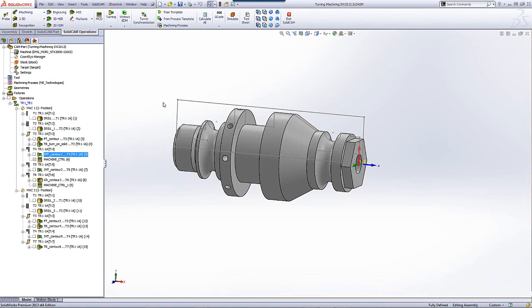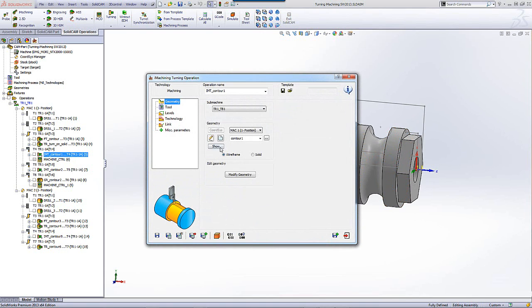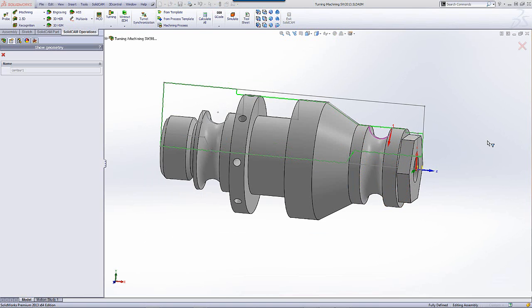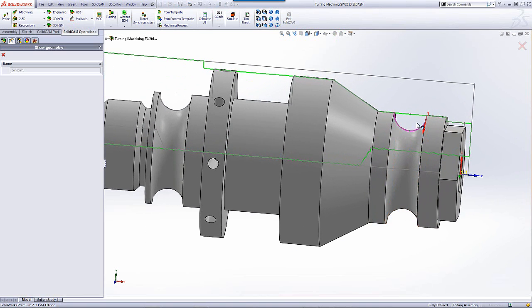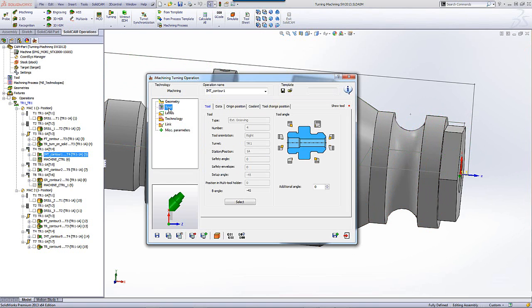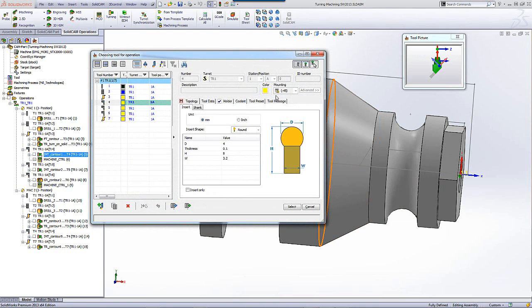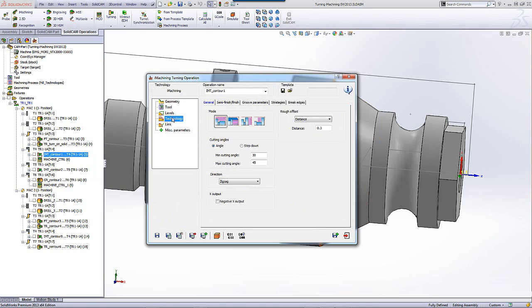Now let's start with the iMachining operation that we want to first do in this area over here. To open up the operation itself, you can see we have our geometry picked out just like any other geometry in turning, working in this particular area over there. The tool in iMachining in turning is always a round tipped tool as shown over there with a ball shape as shown over here. And then we have our technology.